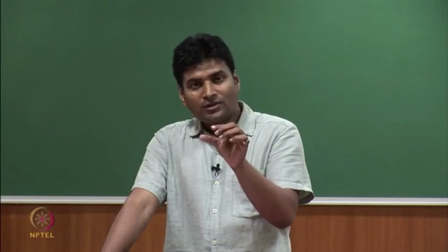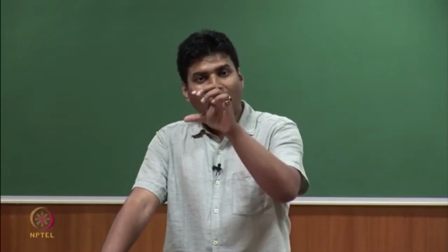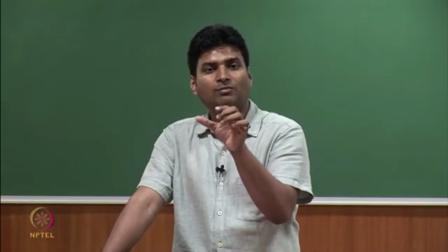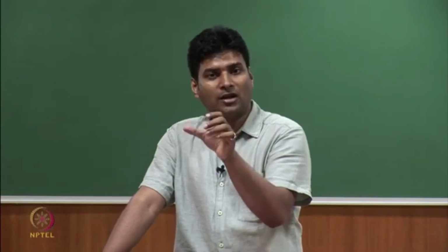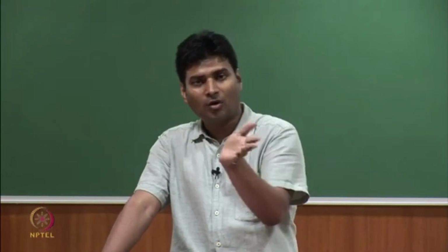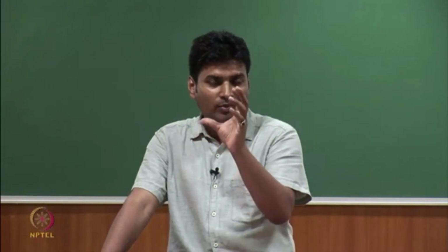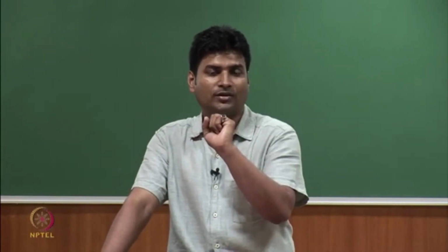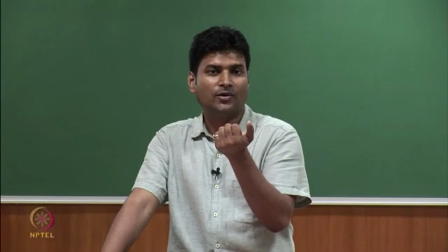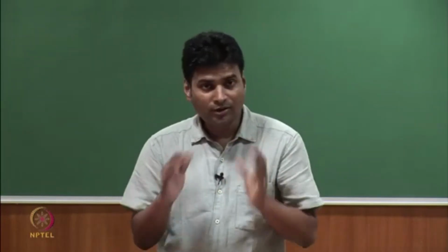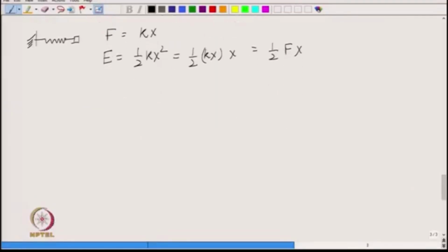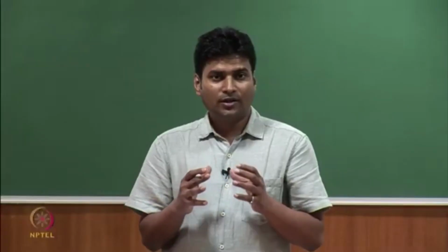It is just that the force in the spring sigma i j does not depend only on the strain in that spring. So, sigma 1 1 does not depend only on epsilon 1 1, it also depends on epsilon 1 2, epsilon 1 3, epsilon 3 3, all the strain components. So, it is a more complicated spring, a coupled kind of spring that you can think of for a 3D elastic body.